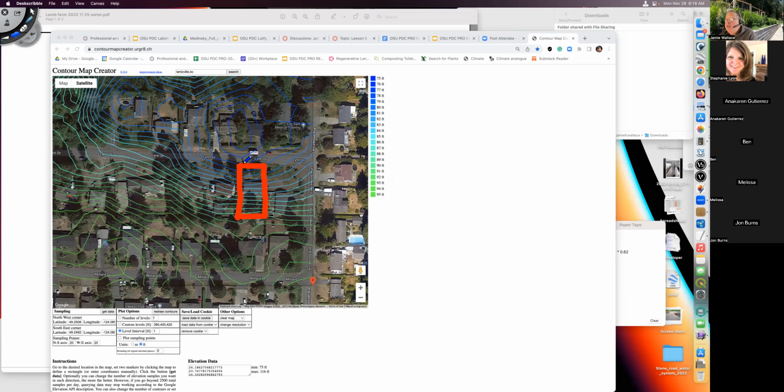What we traditionally will do when we start, and it's very similar to the micro watershed exercise sheet, is start at the bottom or the low point in the project site and calculate where our water is going to come from. You can see the way these lines are going, that if a drop of water hits here, it's going to run at right angle to that contour and clip the corner.